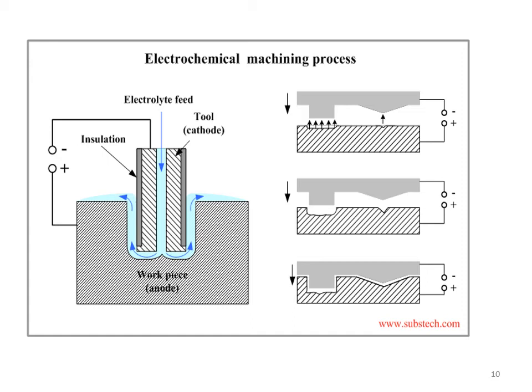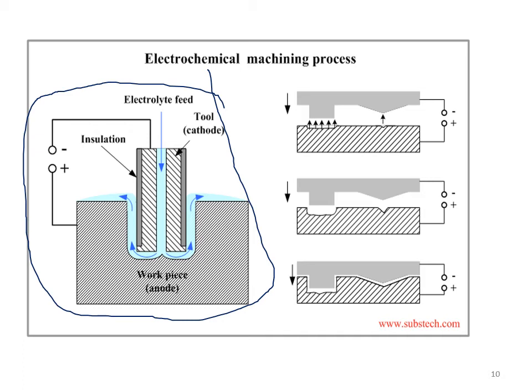If I had just explained electrochemical machining considering a drilling or milling operation, the tool feed direction is downward, which we can observe here. That may be the case for a simple drilling or milling operation, whereas in the case of multiple cross-section areas, unsymmetric different cross sections of machining can be done simultaneously over the workpiece.